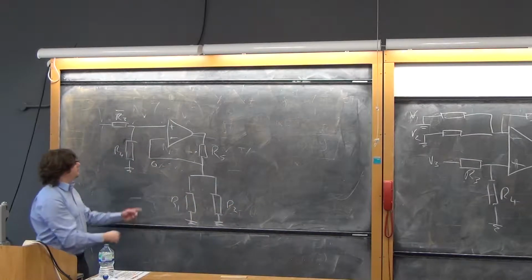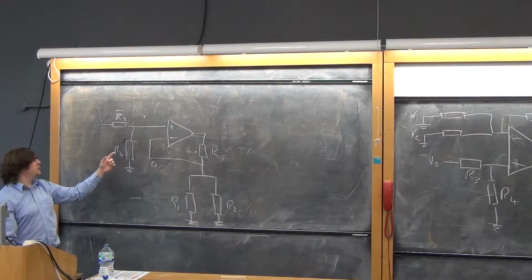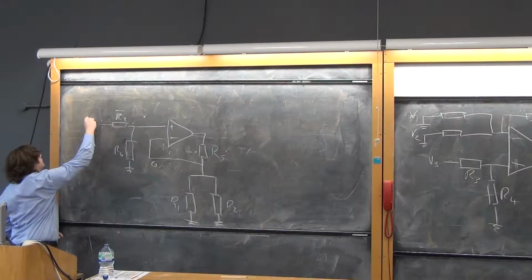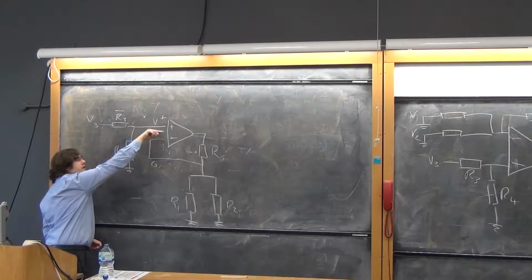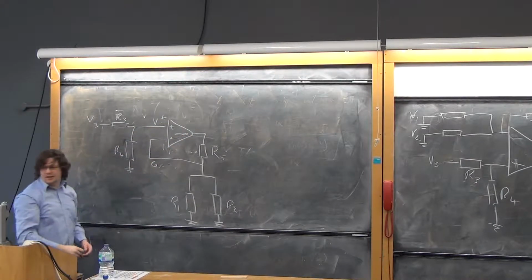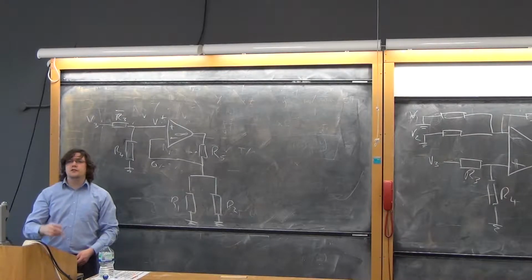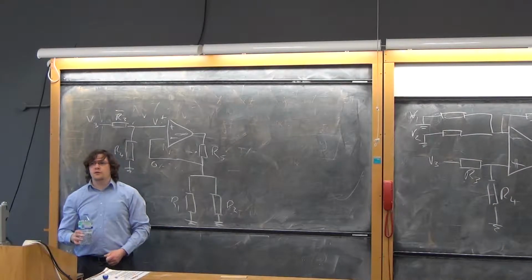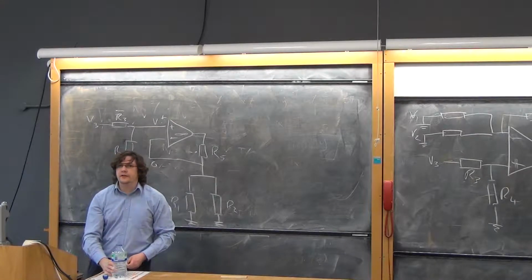So this now looks like a non-inverting amplifier with a potential divider on the front. So you can treat the amplifier and the potential divider separately. So you can say, I'll call this V3 and I'll call that V+. But I know there's a really big impedance looking in there because we've said the gain's infinite. Did we say the gain was infinite? Yeah, we did. For all these sort of multiple input questions, it would be a bit too mean to make you figure it out with a gain that's not infinite. So even if it isn't written there, you can assume it quite safely.